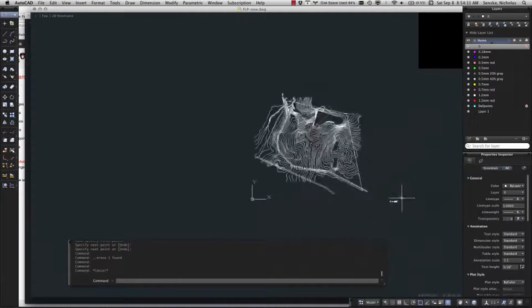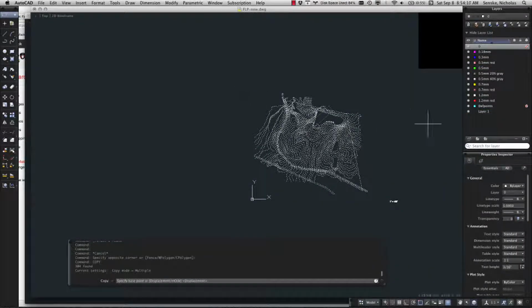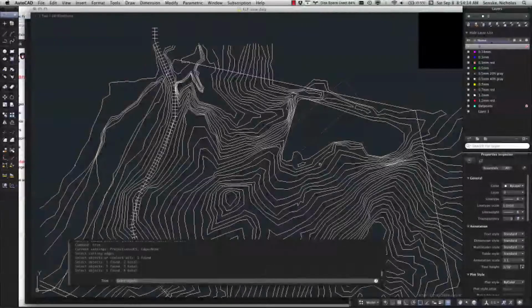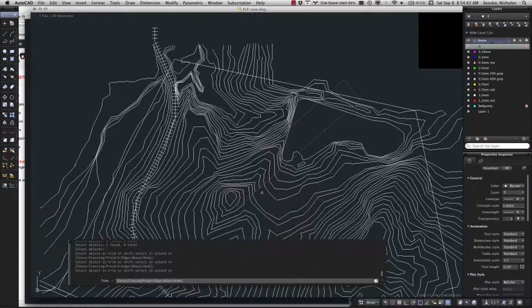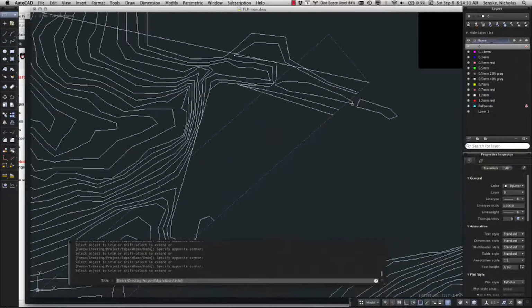It makes sense, if you're going to be doing this, to probably make a copy before you start trimming away at this site. So I'm going to trim, and I'm going to use the box that I just created as my trimming field. For the trim command, I could go through and click each one. You can even select like this, and you can delete that way. And that works pretty well.